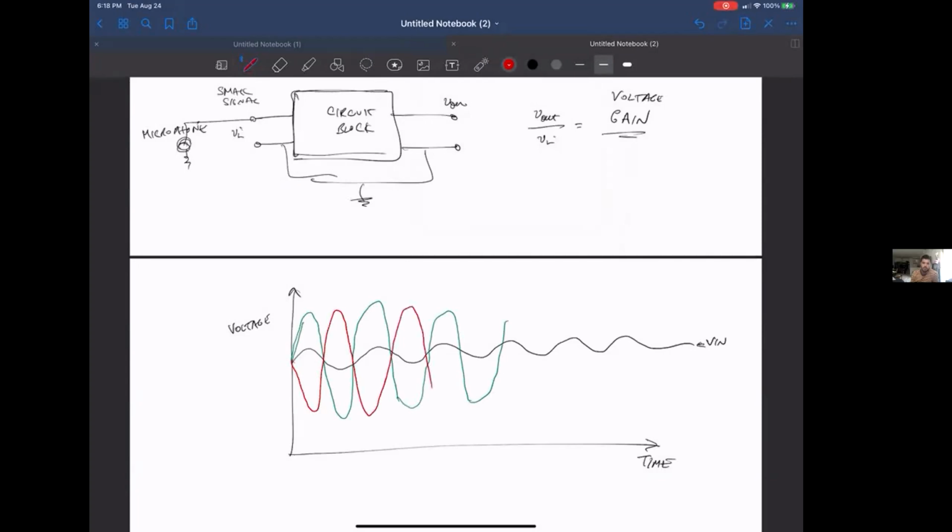So the fact that it's negative, in both cases you're getting current and power from the power supply. It's just that the sign is inverted between the input and the output. A lot of times, like in an audio circuit or video circuit, there are multiple gain stages. If you don't want an inverting gain stage, you'll put an even number of them.